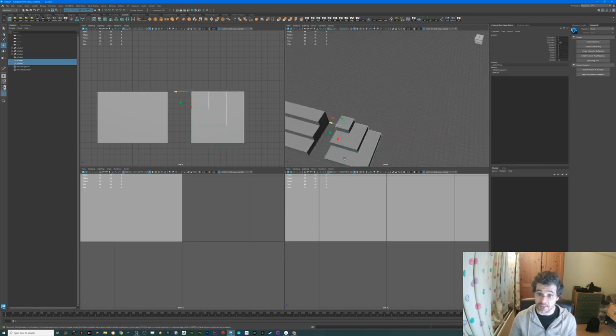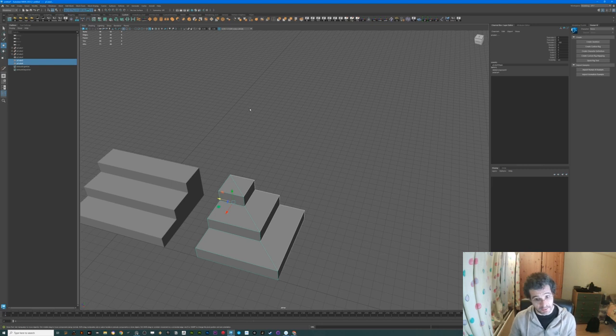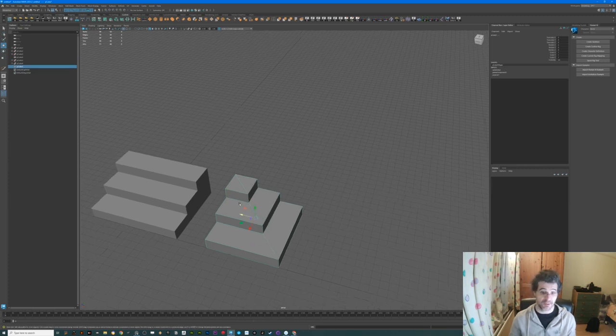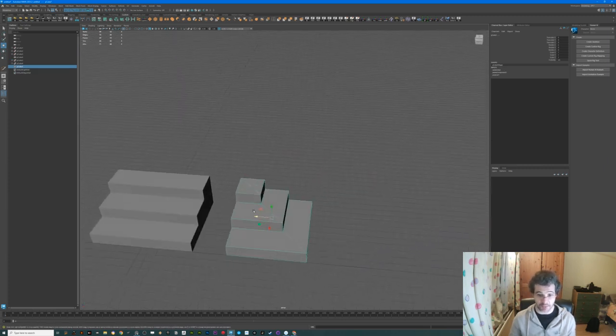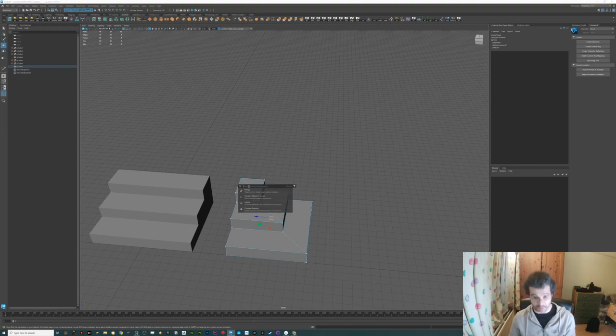I'm going to select these two objects, and I'm going to shift right mouse click and press combine. So now this is only one shape. I'm going to select vertex. I'm going to drag all of these ones, and I am going to merge the vertices that need to be glued. So I'm going to select all of them, press Ctrl F, and I already have merge here.